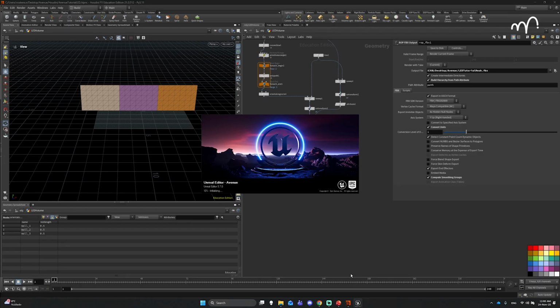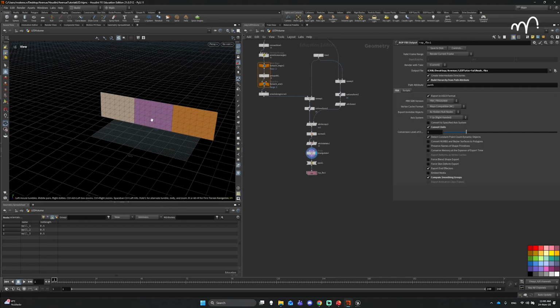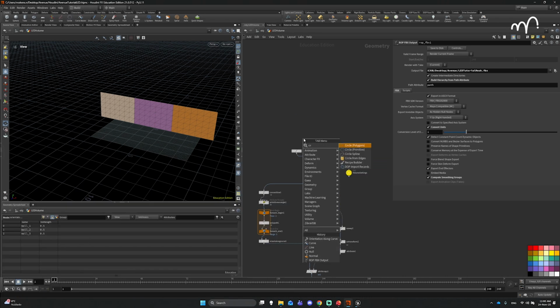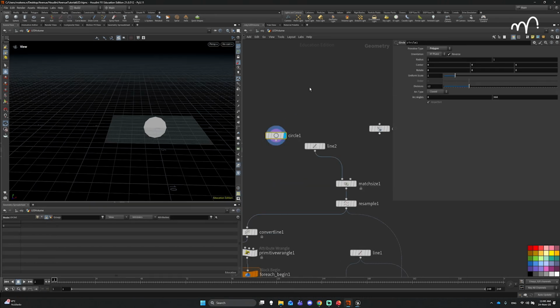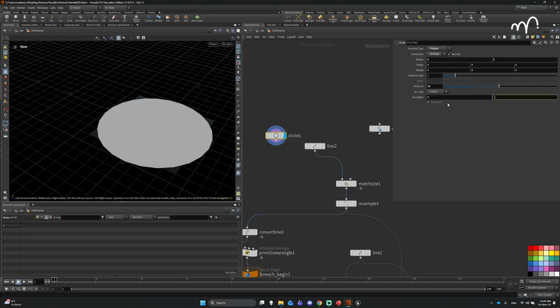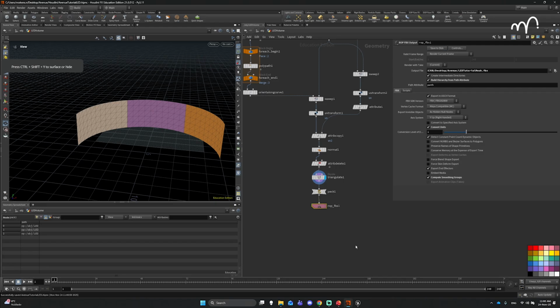So we also need to set up some stuff to make the projections happen, but we're gonna go over it right now. So while this opens, I'm gonna make our curve with circle, which I think is like the most standard one. So just gonna make this again, just make it 5 meters radius, 180 degrees, and then that same logic that we did before. Copy parameter, base relative reference divided by 2 plus 90, I think it was. And it has to be an open arc, obviously. There we go. Cool. So we can save this to disk.